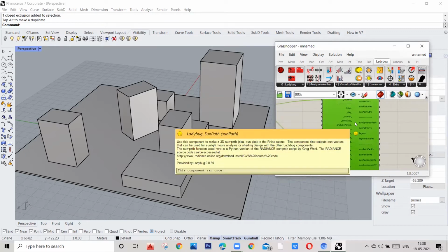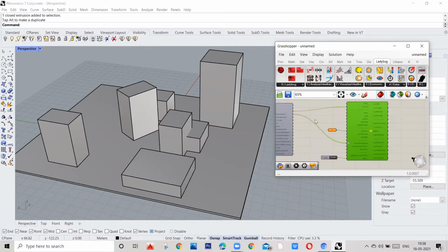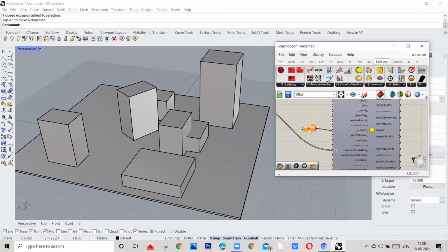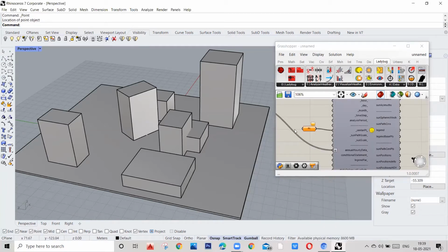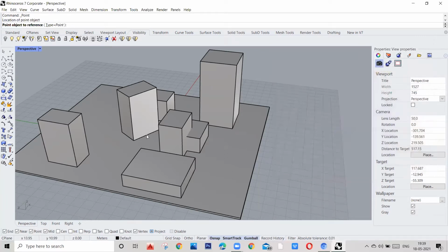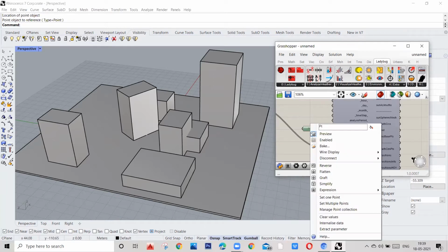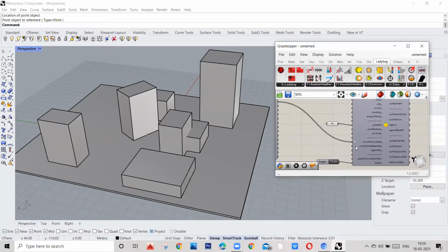After that, same as the previous video, you have to pass that EPW data to Ladybug Sun Path and pass the location, marking the center point. I will just add the point over here, and for now I'm marking it on the edge. Afterwards you can mark it in the middle of the site you want. Okay, done.